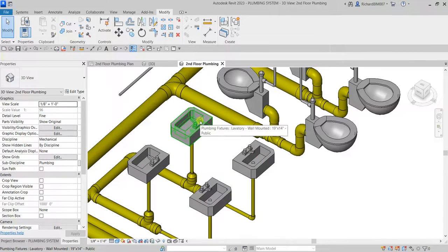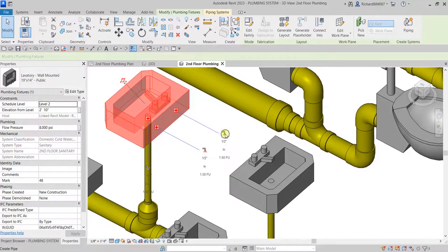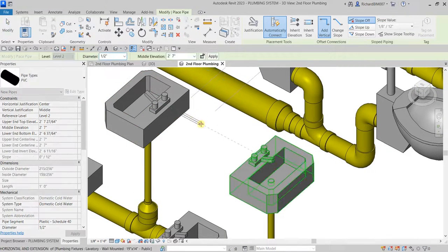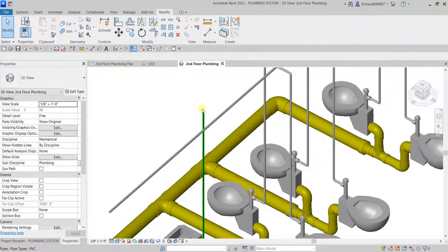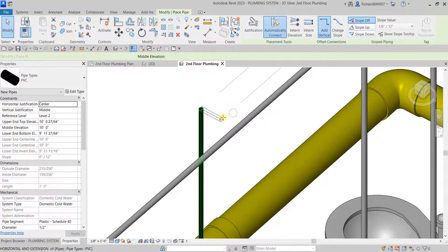So let's click this. Okay, so that's our cold water. So let's click that icon. So let's hold the shift, click, and then let's change this one, 10 feet as well. So 10, apply, there you go. And then you click this one, right click, draw pipe, click.